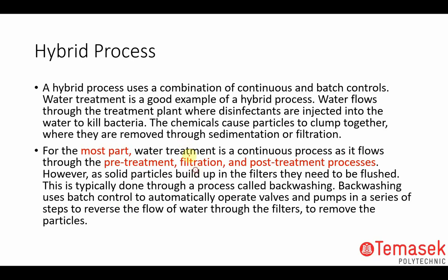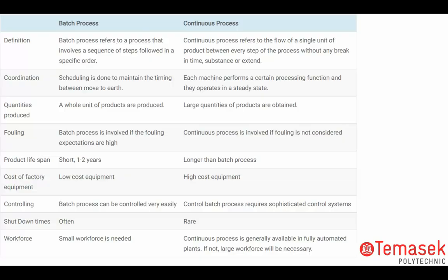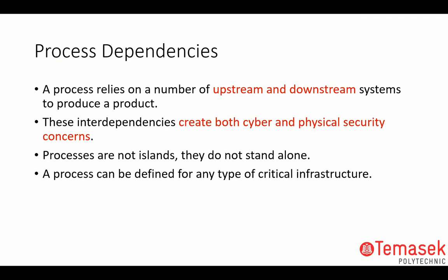If you go to water treatment, it is a continuous process most of the time, but partially it can do some form of batches in between. But a lot of times, not really. Okay, so this is the breakdown between a batch process and a continuous process. Equipment wise, low cost. This one is very high cost, very expensive. Shut down quite often. A batch can be an hour, a batch can be a day. This one is once a year. This one is rare. So that's some of the key things.